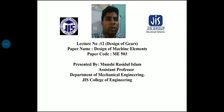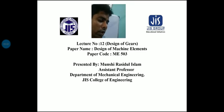And slip means something is lost: time loss, energy loss, everything is lost. So in a gear drive, there is no slipping chance, because power or torque or motion can be transmitted when the two gears are in contact, in meshing condition. Only in that case can power be transmitted.